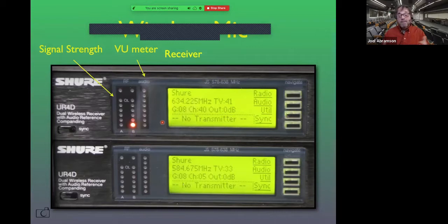And if for some reason there's some interference that happens and that signal gets weak, but the other signal is stronger, then it'll flip to the B one or the A one or wherever it's using. So this one thinks that the B one is the best one, so it's using this, but if A becomes stronger, it will flip over to the A signal. All right. And that's just to help for the robustness of the transmitter signal.